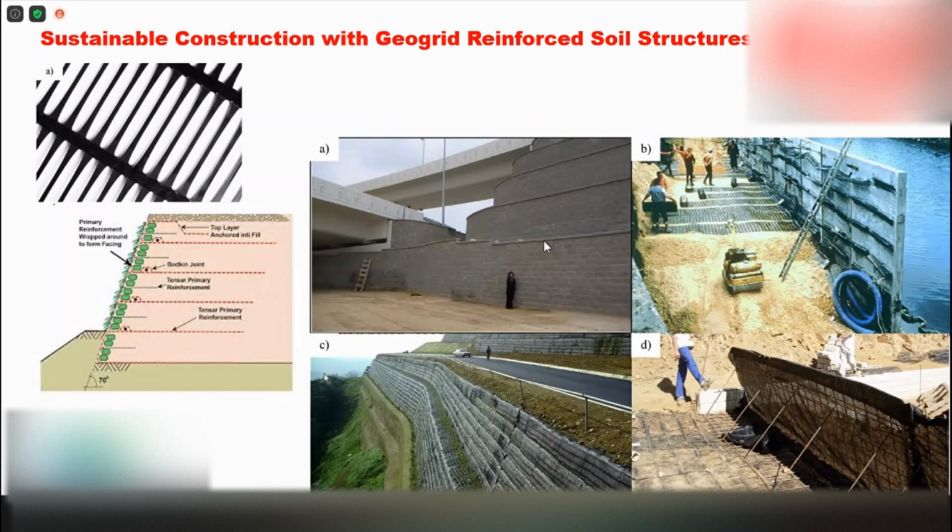Then we can make it look like it is standing vertically and beautifully, and you don't feel there's concrete, because the texture of the interlocking block will look like rock. So you will basically be seeing a rock rubble wall rather than an RC retaining wall. Behind this interlocking block is again this kind of geogrid that's placed horizontally.